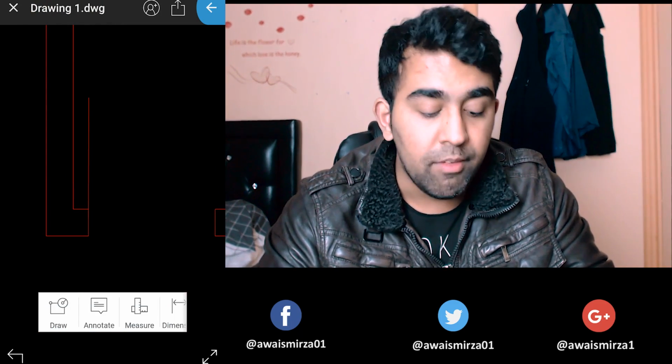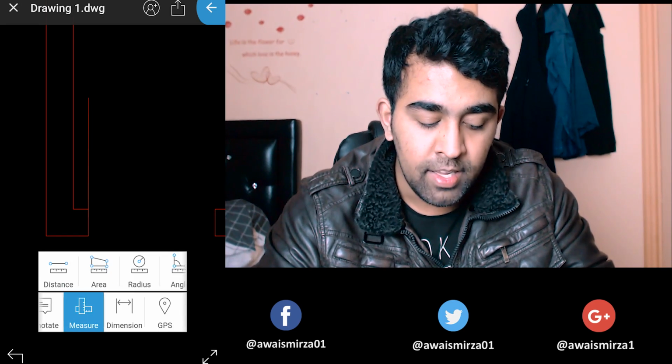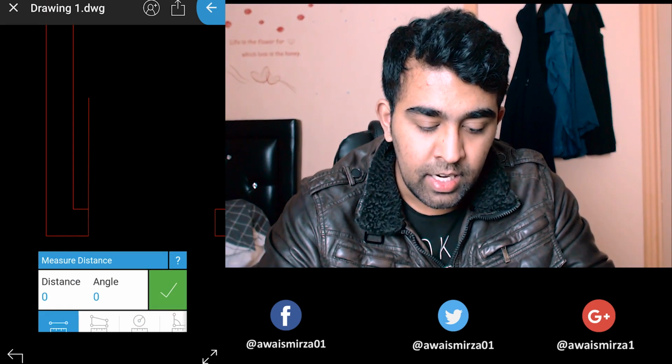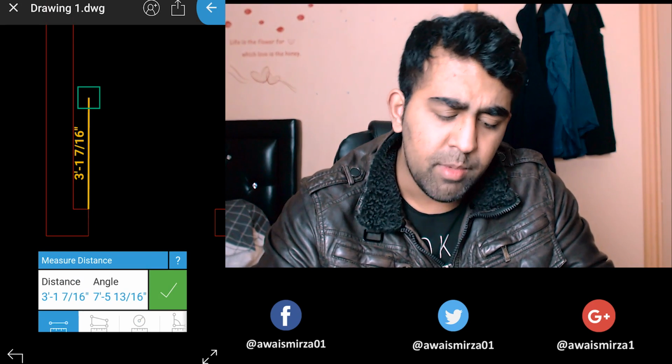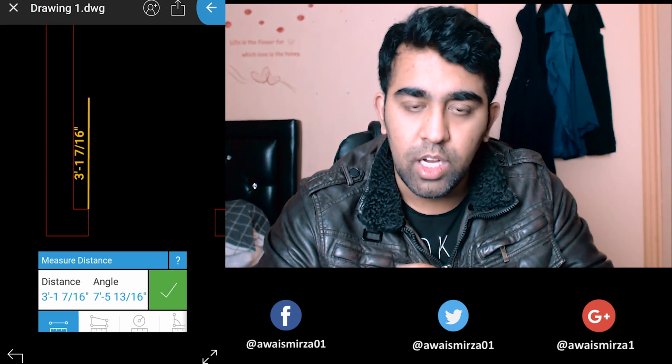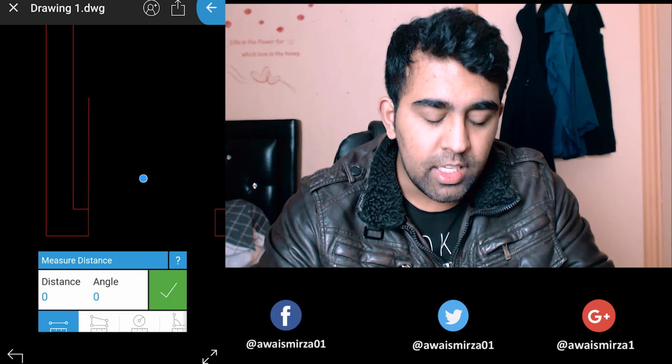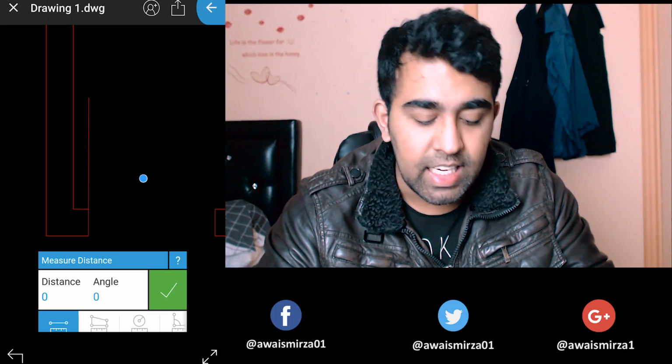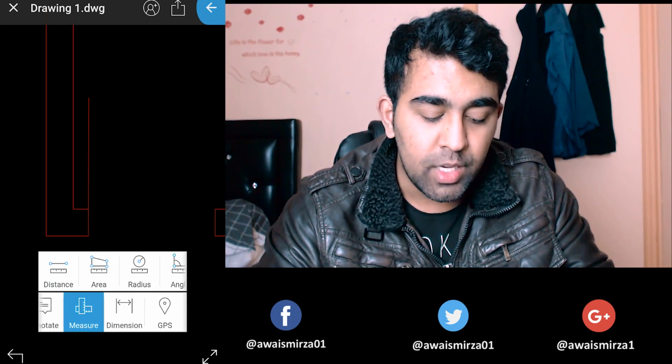Let's check the dimension of it by going to measure panel, a distance, tap here and then tap here. Okay, that's about 3 feet 7 inches. Okay, so that's fine. Okay, so now we're gonna go and select an arc. Okay, tap here to accept that command.